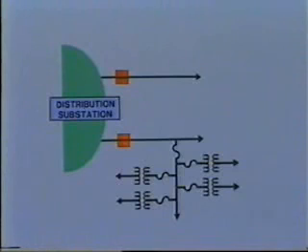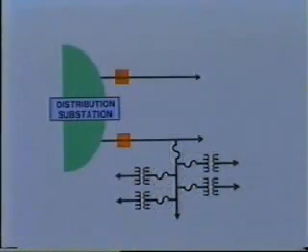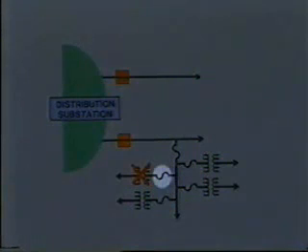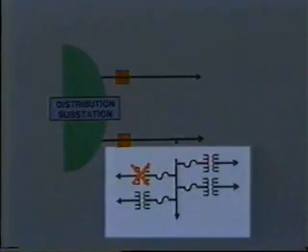Whether the transformer is conventional or comes with protection included, it is important that the transformer fuse and the primary lateral fuse be well coordinated with each other. Why is this? Well, clearly, if a fault occurs in the distribution transformer, we want the transformer fuse to open before this fuse, which protects the system from lateral faults. If the primary lateral fuse blows first, this would cause an unnecessary loss of service to all customers served by the lateral.